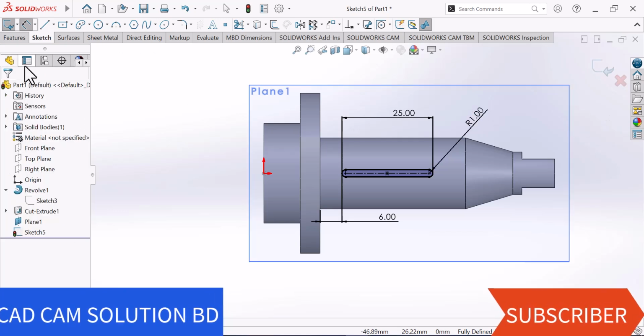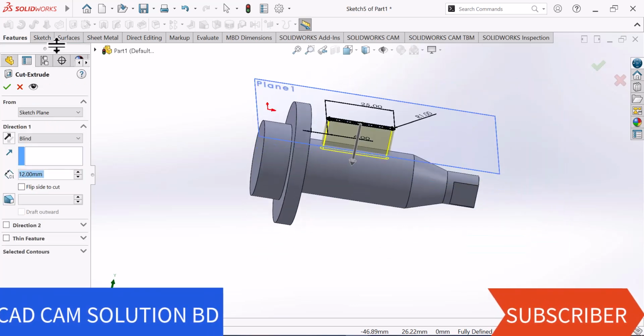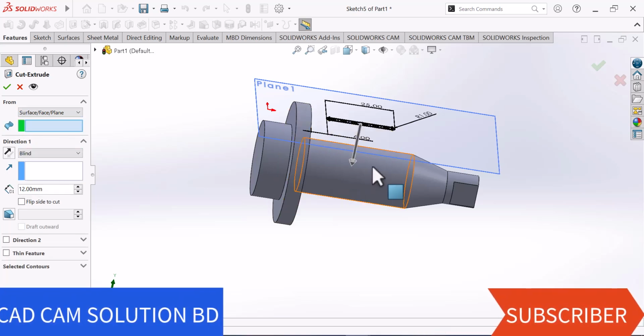Okay. Now go to feature, extrude cut. Now here cut from surface face plane. Now here give the value 1. Okay.